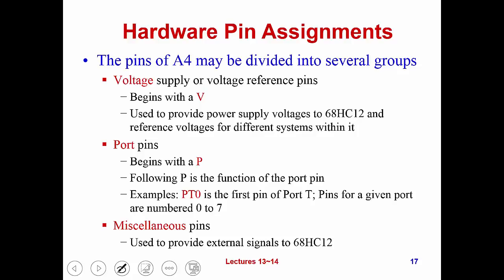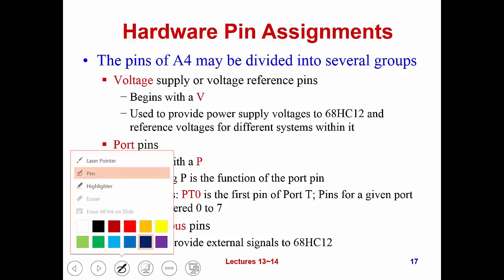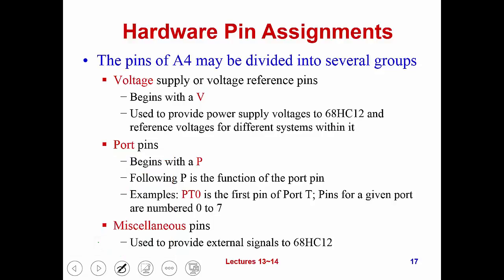Those pins are divided into the voltage supply pins, the voltage pins that begin with V. Some other pins are the port pins that begin with P. We give them names. Then we have some other pins we call miscellaneous pins, which are mainly designed to provide external signals for communication to the 68HC12.